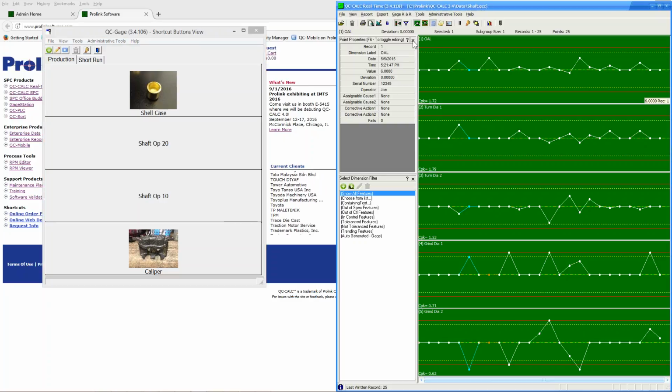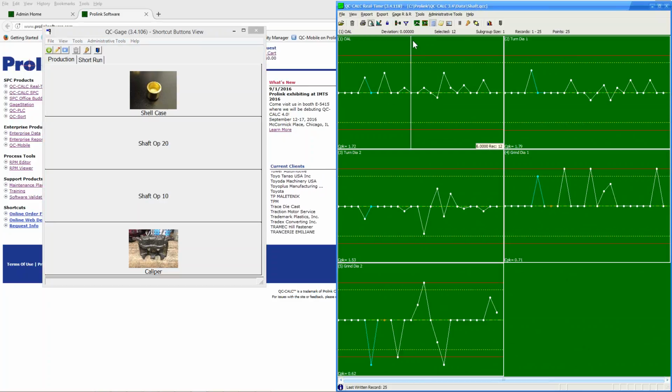Yeah, if we're looking at a particular serial number part, we want to see a report and see all the features on it, right? Yeah, yep. We'll be able to pull that together, right? Right, exactly. And this allows you to put the data all in one data file all together, and it doesn't matter if some of the features were measured on CMM and some were measured out at op10 and some were measured at op20. As long as the serial number is entered when they measure that part, all the data will line up and match up in the one database for that one part, all features.